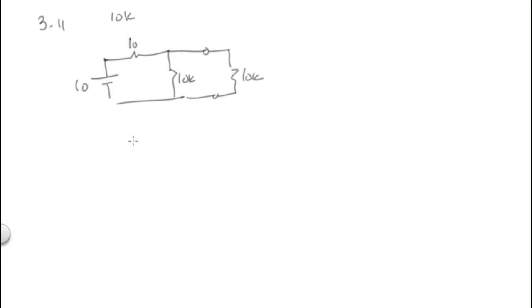So this solves to 5 volts and 5K and then 10K, right? And that's the voltage across that. Or let's go to the current. Current is equal to 5 divided by 15, or 0.33 milliamps. And then the voltage would be 3.33 volts.